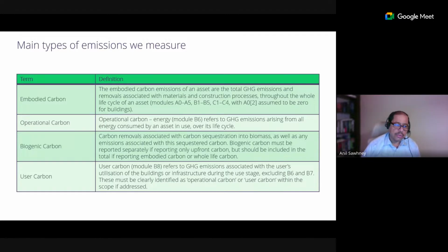We don't have direct control on that. Embodied carbon, I have direct control because I can use low carbon material. Operational carbon, I have direct control. I can use insulated walls, I can use other energy efficiency mechanisms, I can use less water, less energy. It's in my control. Biogenic carbon is again in my control. I can use biogenic material, bio-based material, where I can store carbon rather than emitting carbon. So that's why our focus of a WLC is generally on embodied, operational, and biogenic carbon.